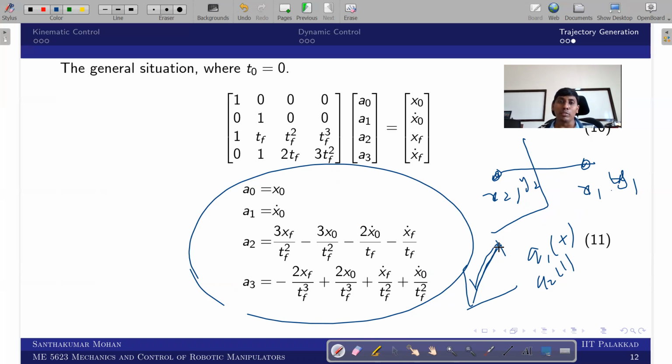Now you can see these are kinematic cases, right? So now you extend to a dynamic case. Then you can see the acceleration in this case would come as infinite at a point, immediately go and come back. In the sense, it is a constant acceleration you have to maintain. This is very difficult in a real actuator. Then we can go to a fifth order polynomial.